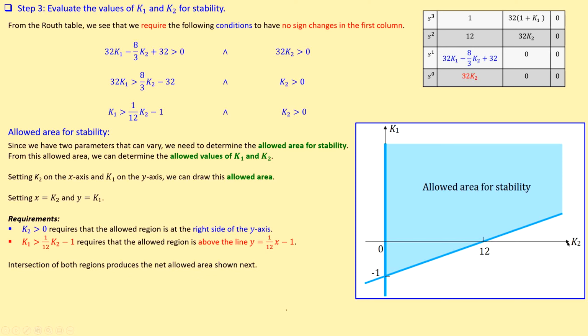So for example, if I take K2 as say 10 around here, then I can of course take for K1 a value between this value and that value. If I go under that value, I have a problem and it will be unstable. That's actually the condition for this system. Now, let's go in more detail and let's look at some cases that will be helpful.